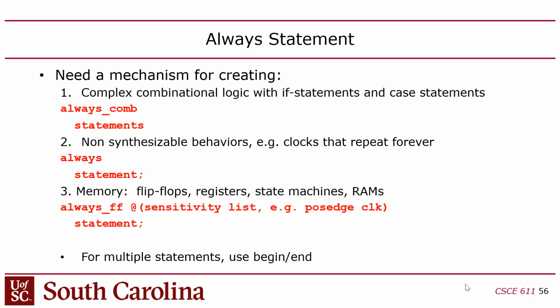Did you guys ever talk about flip-flops in 211? Yep. So basically, a flip-flop is a way to capture a bit and hold it over time. Usually, it's synchronized to a clock. And then RAMs. RAM is a memory structure where it's got memory, but it also has an address. So you've got multiple addresses inside that RAM that are individually addressable. Flip-flops don't have an address. Flip-flops are memory elements without an address. RAMs are memory elements with an address. And you can implement both with an always statement.